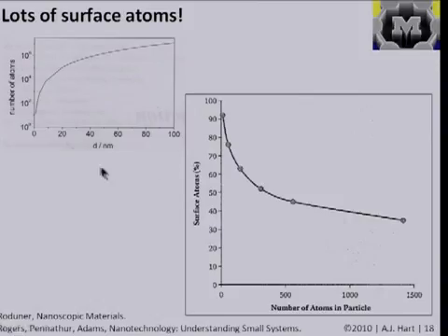can be counted as you get down to the nanoscale. If we think that we're down at this scale of having, say, 100 to 1,000 atoms, and we look at a different kind of simple plot for a sphere, where we look at the percentage of surface atoms versus the total number of atoms, you see that in the nanometer size range, you have maybe tens of percents of your atoms on the surface, and that has a big difference on the properties and the characteristics of the structure.